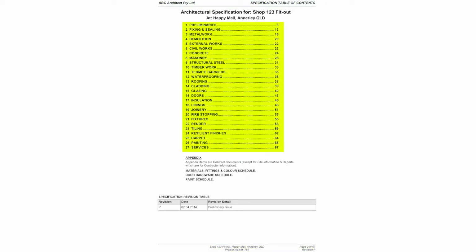The 27 sections should remain if possible in every spec done. This has two advantages. First is project-to-project familiarity. Second, when a section is not needed, it stays but states that it is not applicable, so contractors quickly know what is not in a project without having to do full document analysis.